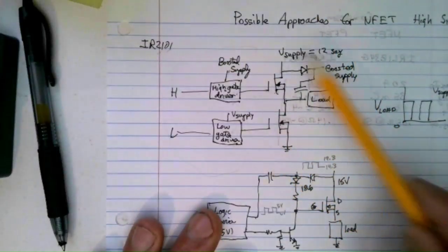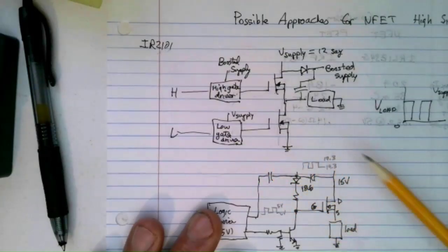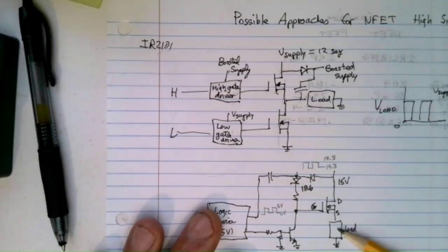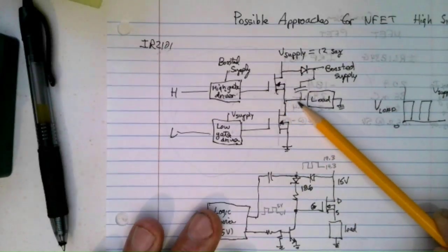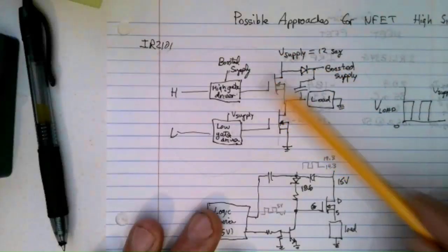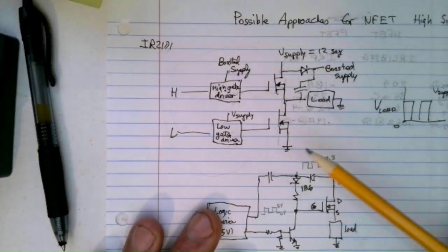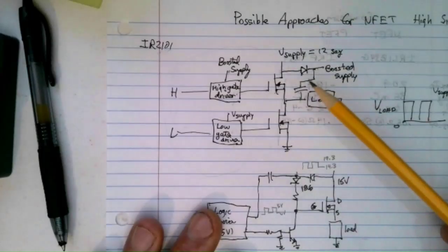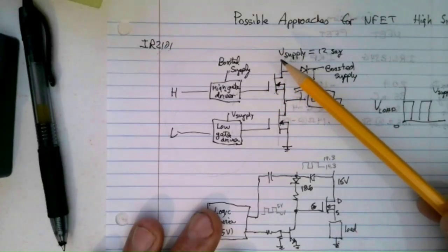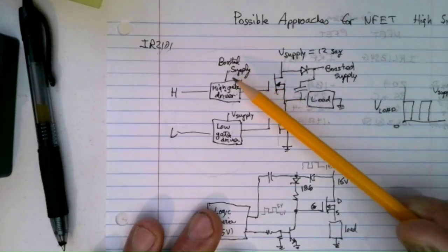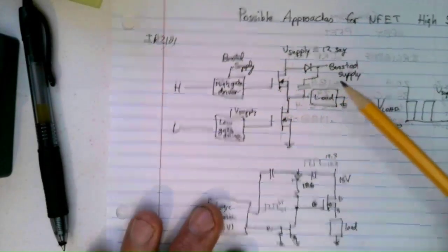Okay. Now, suppose you just want to use an NFET to turn on a load, on and off, maybe once every 10 minutes or once every hour or something like that, and you don't have an AC source here that you can steal some of to build this little power supply. Because really, that's what we're doing. We're building another power supply. If you happen to have another power supply, and it's higher than 12 volts, let's say for this application you have a 20 volt power supply, hey, you could use that, and then you're good to go.